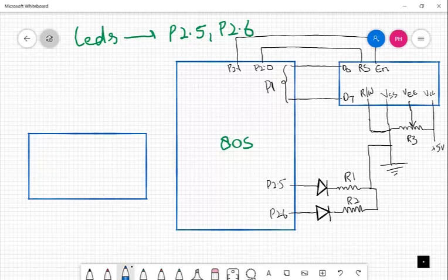So there are 8 data pins that we directly connect to the microcontroller. From D0 to D7, we are connecting these to port 3. We have already discussed that. And then there are some other pins. There's a read pin, that's an input to the ADC.